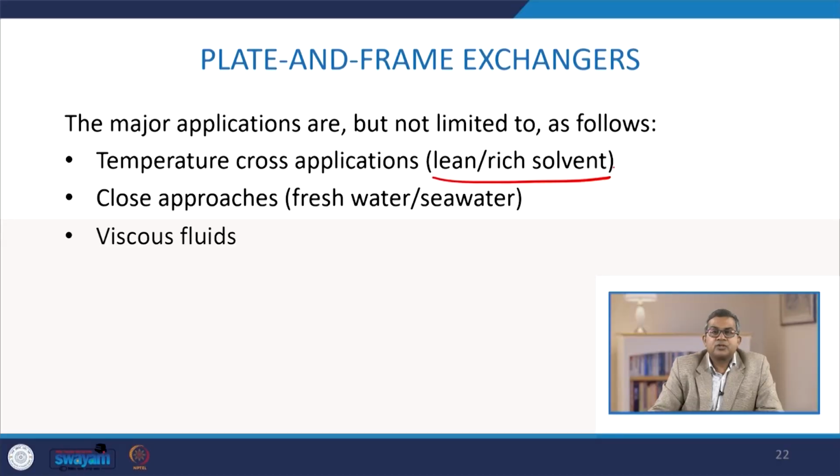Now the major applications are, but not limited to, temperature cross applications for lean and rich solvent, close approaches applicable to fresh water to sea water to fresh water, and different types of viscous fluids. For this, sometimes you require a sterilized surface, sometimes a polished surface.